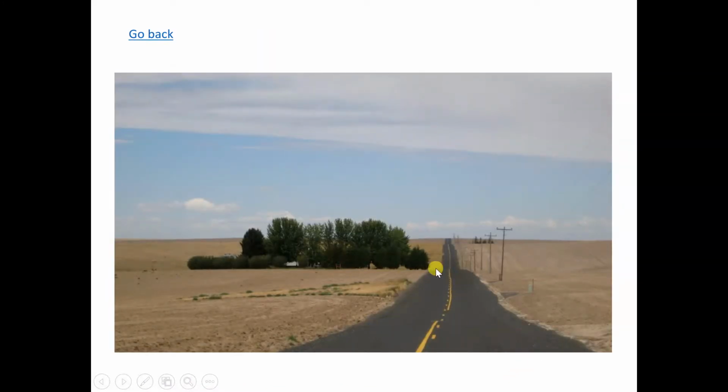This one is a straight road, but if it's up and down, it's not so pleasing compared to a straight line. It's straight, so there's no vertical curve, so everything is straight. You can see further straight ahead, because in this one, some of the vehicles may be hidden at the valley here. Okay, but cost wise, if you have to fill up every valley, it's going to cost quite a lot of money.